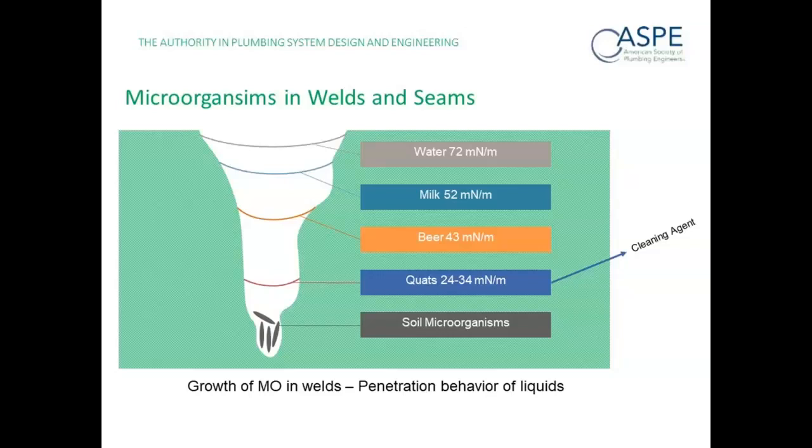And the harborage point, the main one in any plant or facility, is concrete. So if you can cover up the concrete and keep it dry, then you're eliminating a petri dish overall. So that's why those drain connections are so important. You might have just a very small hole in that transition between the floor and the drain, and the next thing you know, underneath it, you've created a nice little environment for bacteria to grow and replicate. And if we can eliminate those, that's really the critical piece.